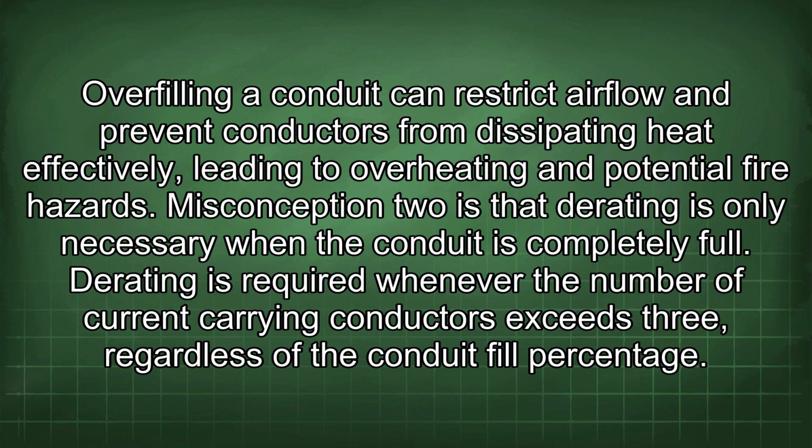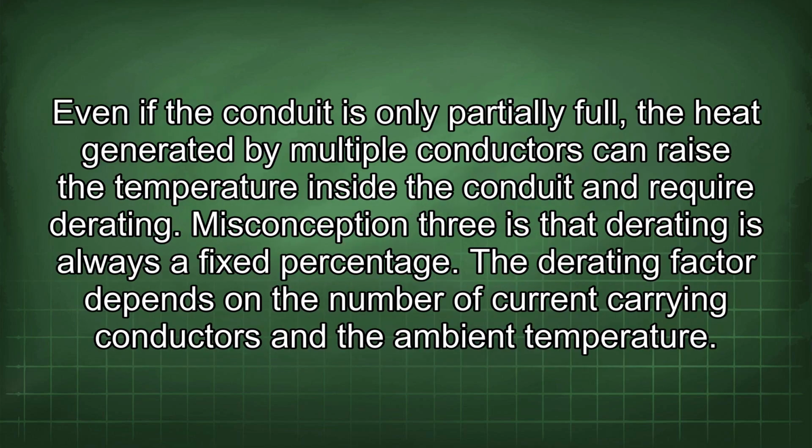Misconception 2 is that derating is only necessary when the conduit is completely full. Derating is required whenever the number of current-carrying conductors exceeds 3, regardless of the conduit fill percentage. Even if the conduit is only partially full, the heat generated by multiple conductors can raise the temperature inside the conduit and require derating. Misconception 3 is that derating is always a fixed percentage.